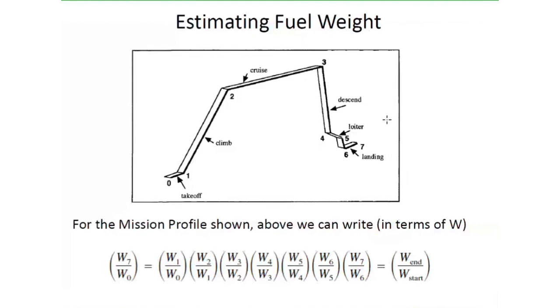For that, you need multiple things. You need to estimate the lift-drag ratio, and you need the specific fuel consumption. Okay, the lift-drag ratio is difficult to estimate at this point because you have no other parameter. So what you can do is take the specific fuel consumption and the type of jet engine you have chosen, and say that okay, this engine is going to fly for 6 hours, and roughly this many kilonewtons of thrust I need. With 6 hours, you get a fuel consumption estimate. And that may not be the most ideal, in the sense that you haven't used the actual range equation in terms of L by D and all that. But to get a fuel consumption estimate, that is good enough.